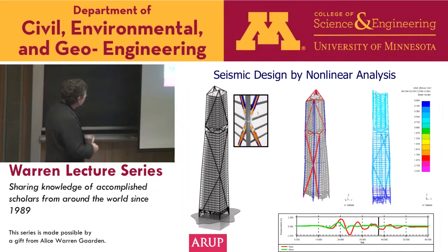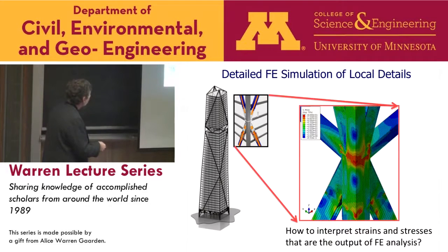But then when you get into some of the details of that, say this connection where these mega braces come in, you need very detailed finite elements there, because again, these things are too big to test in a laboratory, so to validate whether these things will work, that is, not fracture under the applied loads. So this is kind of an ideal situation where we need these better ductile fracture models.